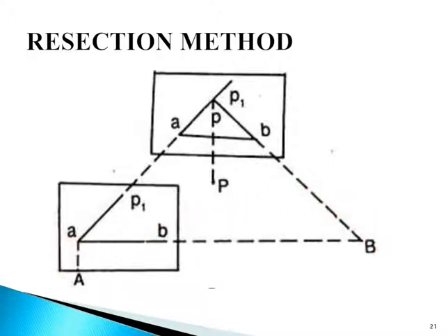Then the table is set up at station A. It is leveled, centered, and oriented by bisecting the ranging rod at B, and the table is then clamped with the alidade touching point A, small a. The ranging rod at P is bisected and a ray is drawn. Then a point p1, small p1, is marked on the ray by estimating with the eye. So we bisect the ranging rod at P, rays are drawn, and accordingly point p1 is marked on the sheet.